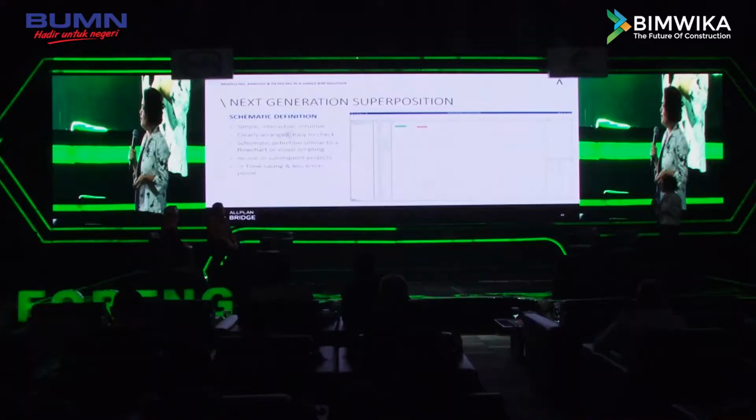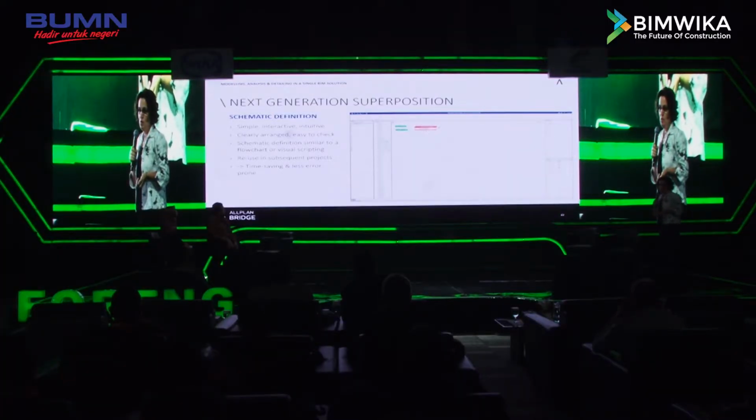Very innovative here is the superposition. All bridge engineers, we know that the loads are not enough. We need to combine those loads with different factors, favorable, unfavorable, in superposition files. And those superposition files here are combined with each other very interactively and user-friendly. The green are load cases, the blue are superposition files. You can change those extremely easily, and this is time-saving, gives an overview, and is always changeable.